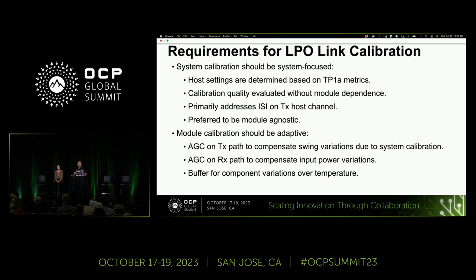So like we talked about, ideally, as we proposed, the system calibration should be system focused. That means the host setting should be independent of the LPO module. In this talk, we are proposing to determine the host setting based on the TP1 metric. And in a moment, we'll talk about what that means. And this is mainly addressing the ISI on the TX channel at the host side only.